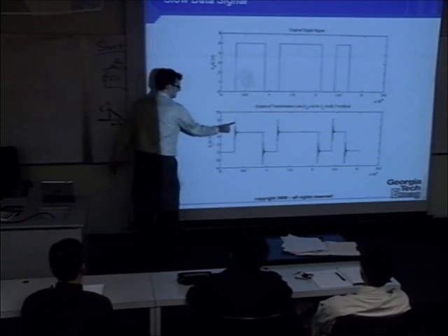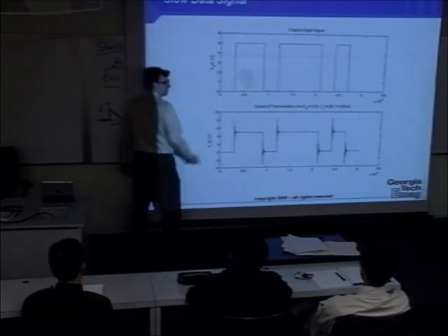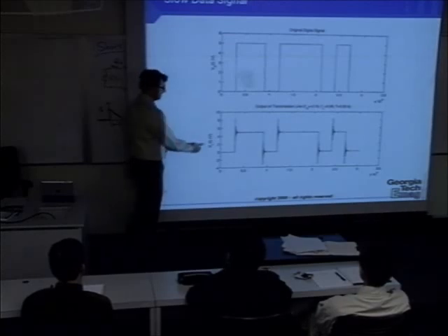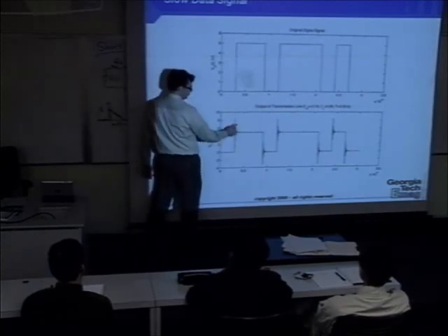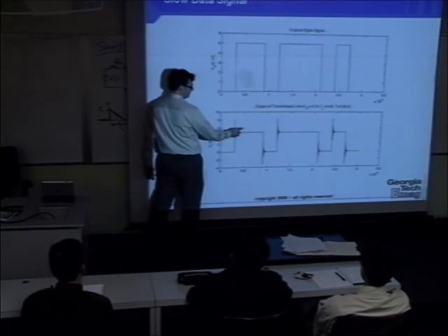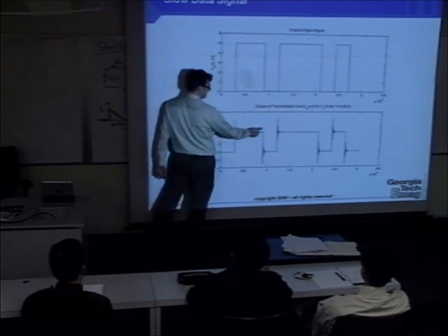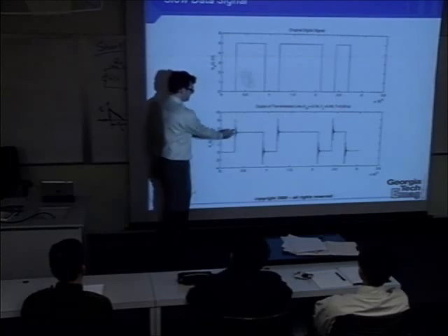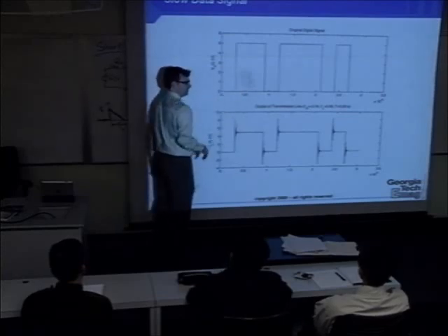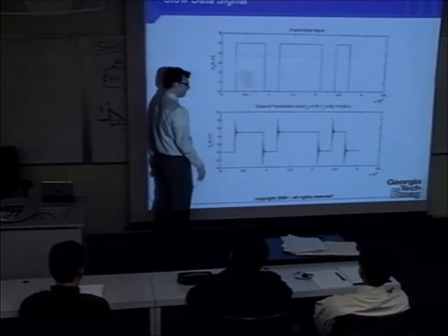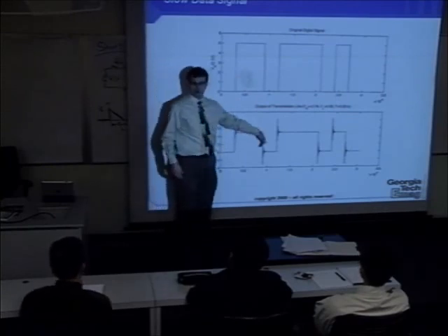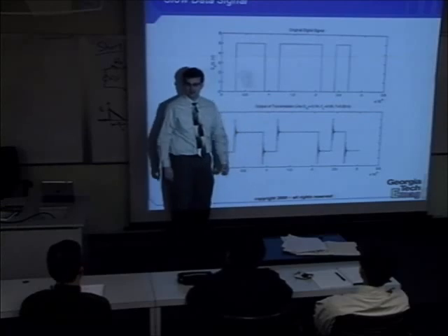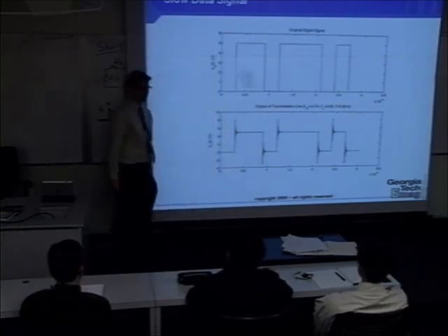See, look at this. This is very fast changes, high frequency content. This square wave, it's got a sharp transition, but for the most part, it's a really low frequency signal. So you put this signal through a low pass filter, what will happen is this high frequency stuff will be stopped. It won't even pass through. The only thing you might do is just round the corners a little bit. Introduce a little Gibbs phenomena on the edges. Not that big of a deal.